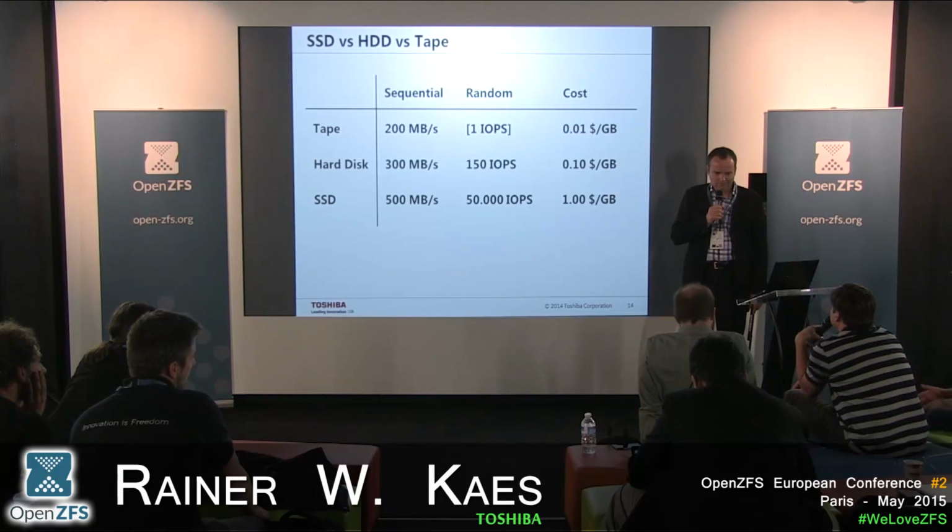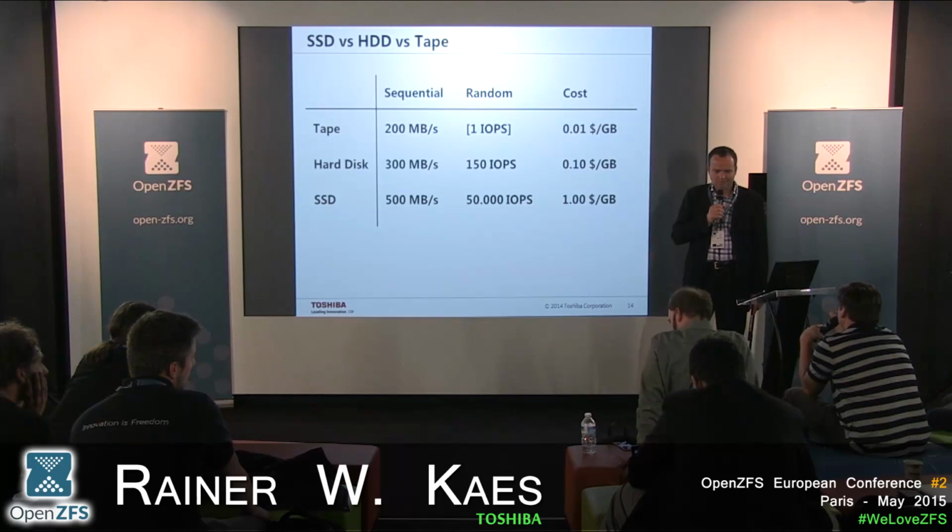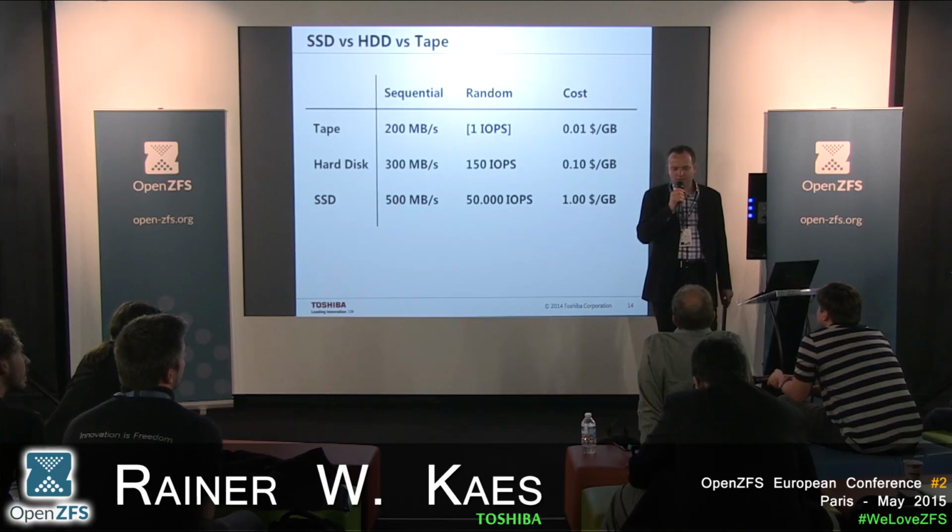Where do you see the size of pages going in flash technology, as well as the erase blocks? And is that information going to be accessible to software developers, to be able to query the devices to actually make smarter decisions? Well, it's in our data sheet. We publish this information. At the moment, SSDs are between 256 and 512. With new generations of 3D structures, it will probably go up to 1024, 2048. But then it also depends on the decisions of the flash designer and the trade-offs of the raw flash designer, and these guys are far away from us. So we don't really know, it's deep down physics. We don't really know where the direction goes.